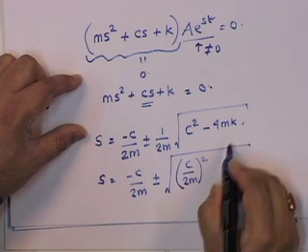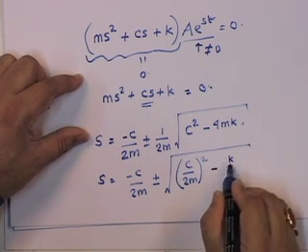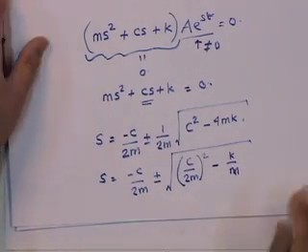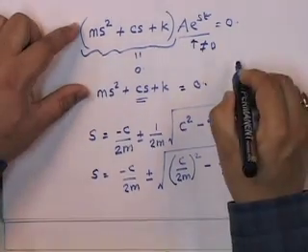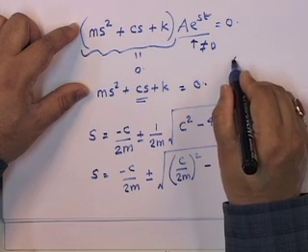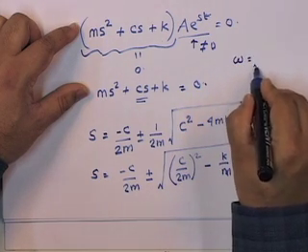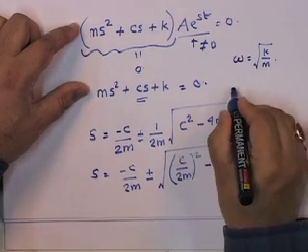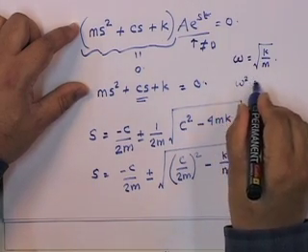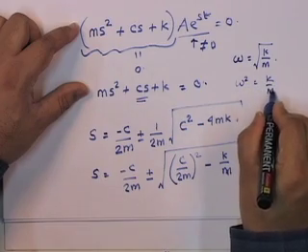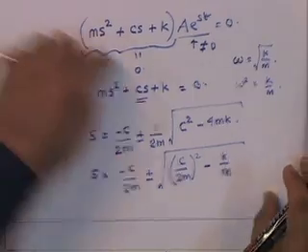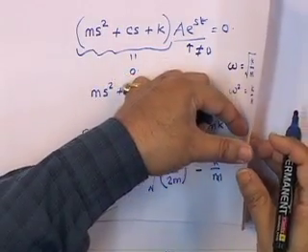So, when you put 4m squared over here, you get k upon m. Now, note that earlier we have defined the natural frequency of the structure omega as square root of k upon m, right. So, which basically means omega squared is equal to k upon m. So, I can substitute this here, and what I get is this solution.